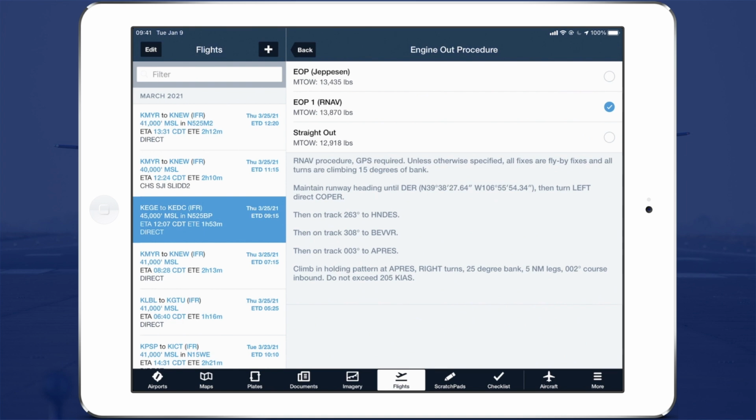That's interesting. Yeah, so once the aircraft has declared the emergency and you're within the controller's minimum vectoring altitude, the controller then is able to start working you vectors back to the airport or back to an emergency return airport, which may or may not be your departure airport. So my goal when I'm flying an EOP is really to get into the minimum vectoring altitude of air traffic control such that they're able to send me where they want to, and they're taking control of obstacle and terrain separation requirements that I have my hands full trying to meet.